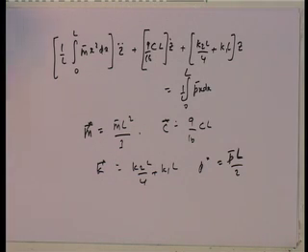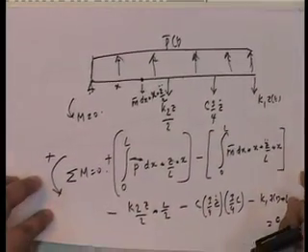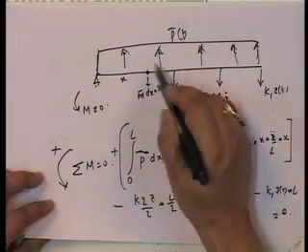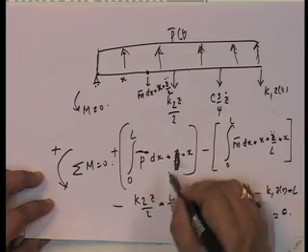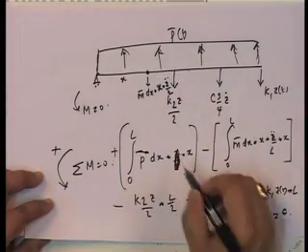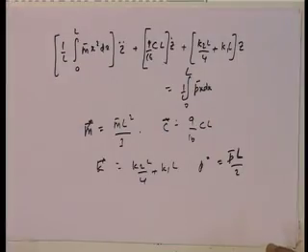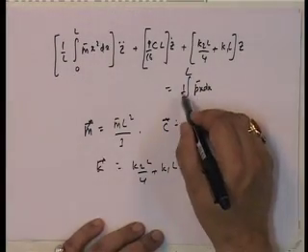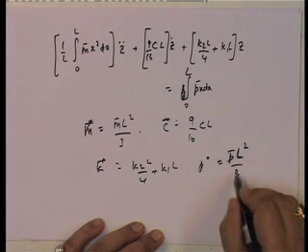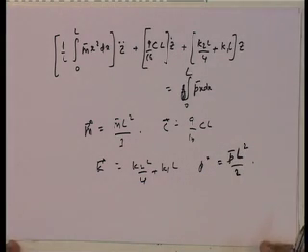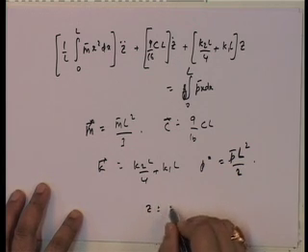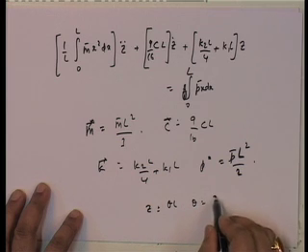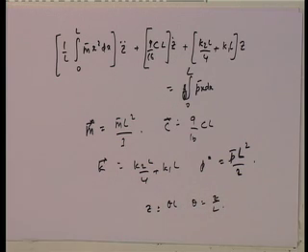I am sorry, if I get back to this, I just want to re-establish this. This is p bar x dx, okay, and z by L does not come into the picture. p bar x is the load, and that into x is my this thing. So, that is why this becomes p bar x, there is no 1 by L. So, I get p bar L squared upon 2. Okay. So, that is my p star. Now, you will ask me that this looks different from the other one. Well, if you substitute the fact that z is equal to theta L and put theta equal to z by L, you will see that it is the same equation.